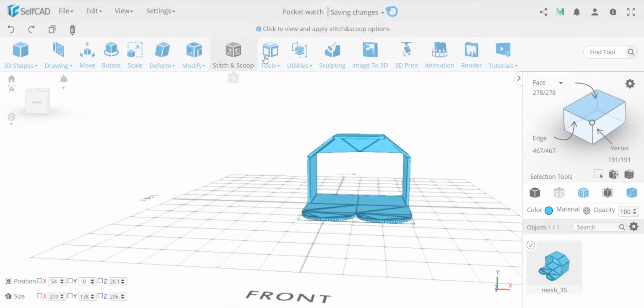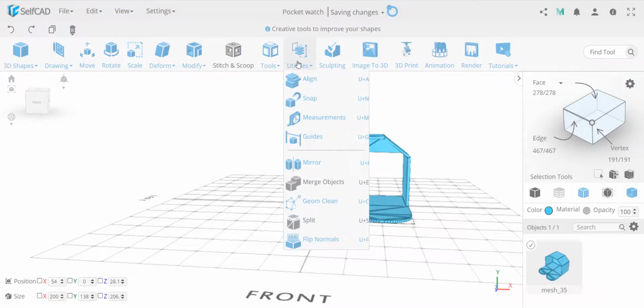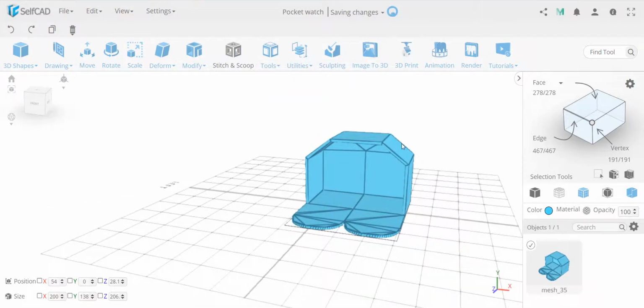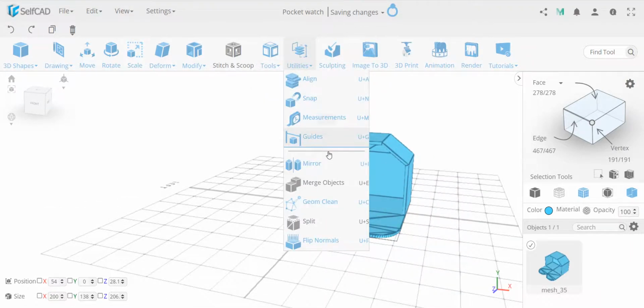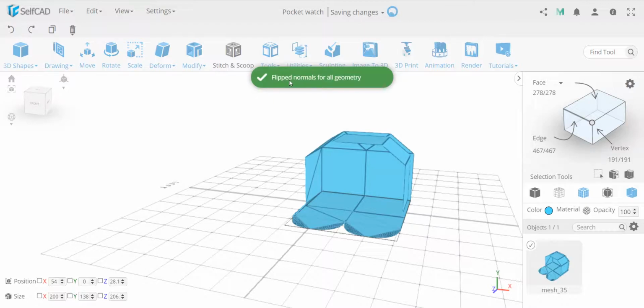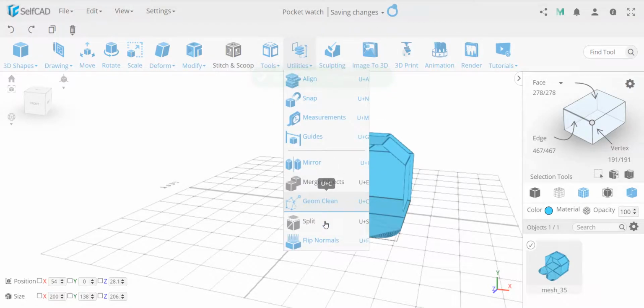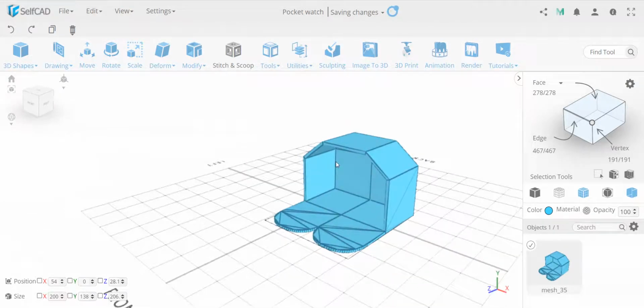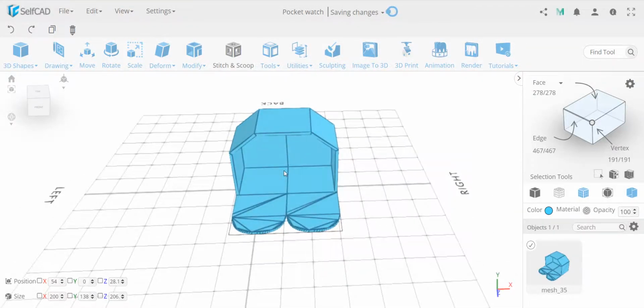Okay, deselected, let's go to this mode. Now if you go again to flip normals as an entire object, not just that face, it will first try to fix it. You see fixed flip normals orientation. Only once it's completely fixed, if you go flip normals, then it will flip the entire object, and the next time it will flip it back. So that's basically how this works. This is mostly the part on how you convert.